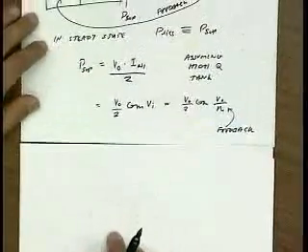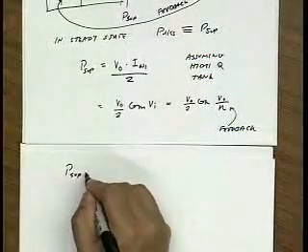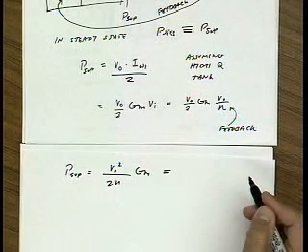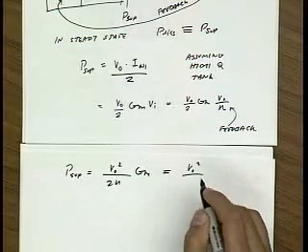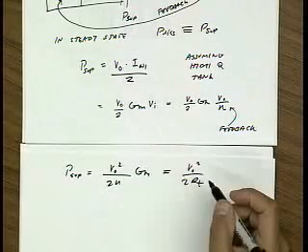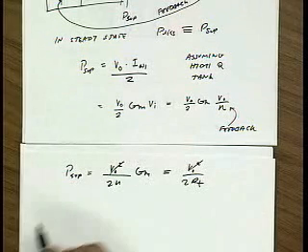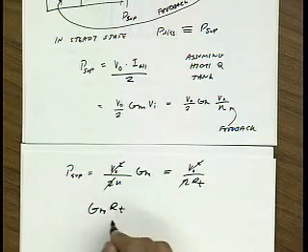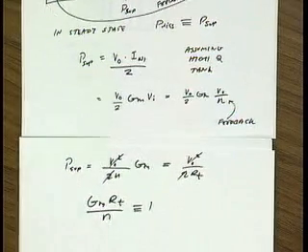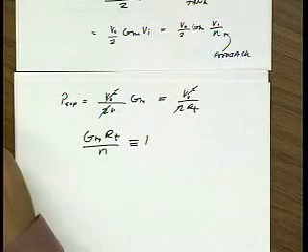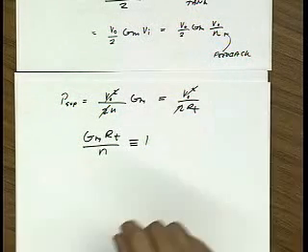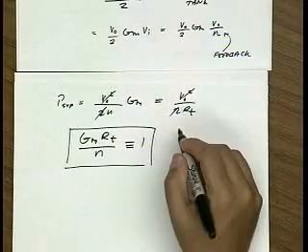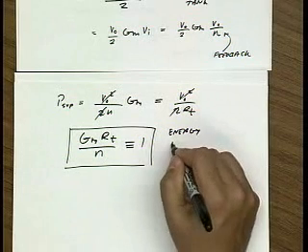All right, well, this is the power. So the power being supplied is V out squared over 2N times GM, and the power being dissipated by the tank is V out squared over 2RT. And so we see that V out drops out, the factor of 2 drops out, and we have an equation: GM RT over N is therefore identically equal to 1. And this is the same equation that we derived last lecture, but now through a different perspective. So if this condition is satisfied, then we have energy balance.